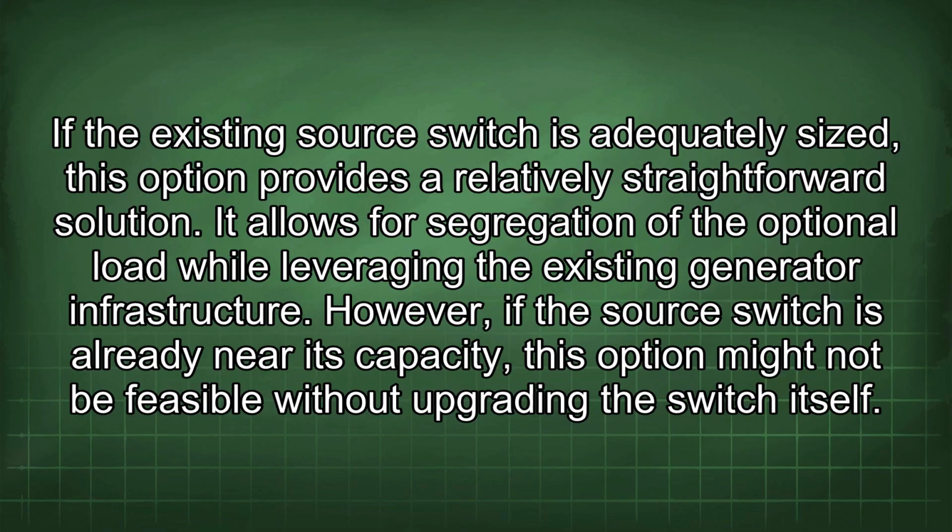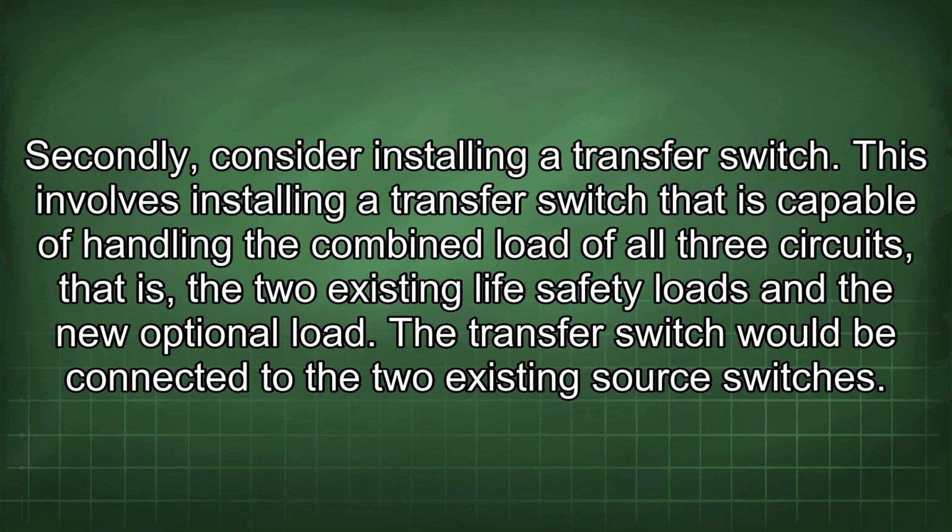It allows for segregation of the optional load while leveraging the existing generator infrastructure. However, if the source switch is already near its capacity, this option might not be feasible without upgrading the switch itself. Secondly, consider installing a transfer switch.